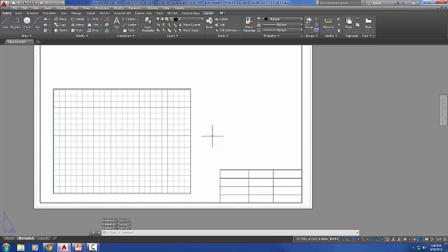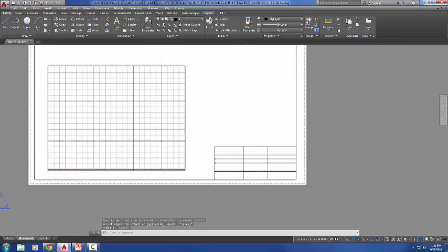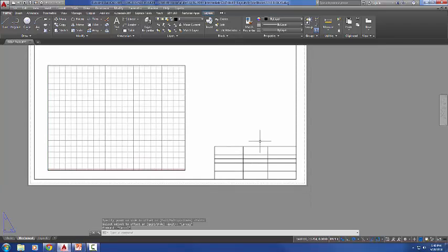And it says to go ahead and offset the second horizontal line down 0.25. So I'm going to offset 0.25 from here to here. Now it says to trim as necessary to make it look like the block. So I'm going to do the trim command. If you press enter right now, instead of selecting your cutting edges, everything you click on will disappear. So trim, trim. Oops, I should have trimmed right there. I need to go back and erase that line.